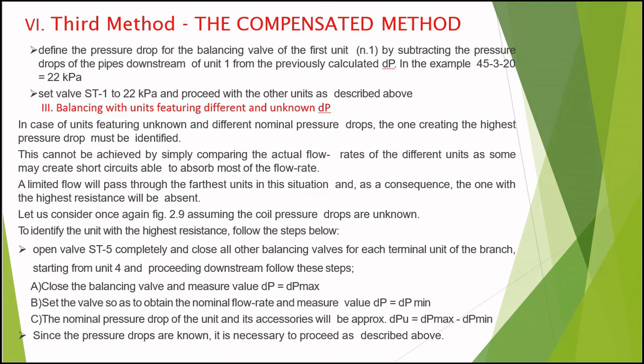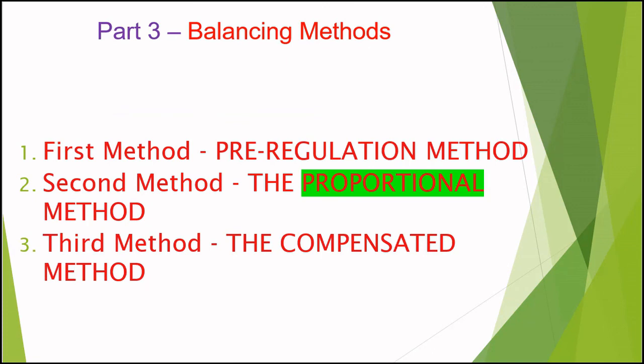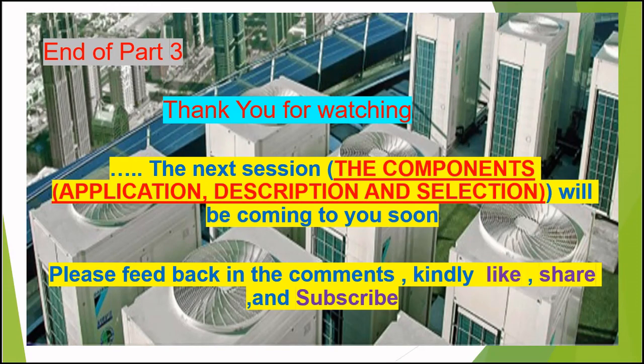This presentation described the 3 important methods in balancing of hydronic systems, balancing methods of HVAC systems, which are the pre-regulation method, the proportional method, and last the compensation method. Thank you for watching this video.